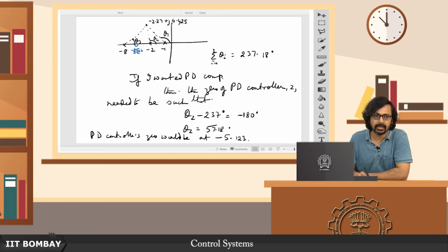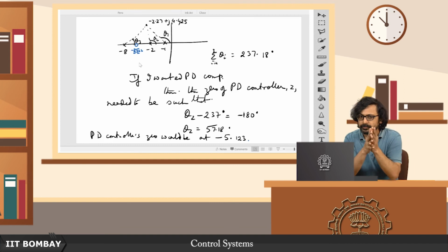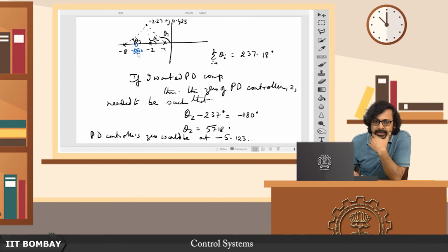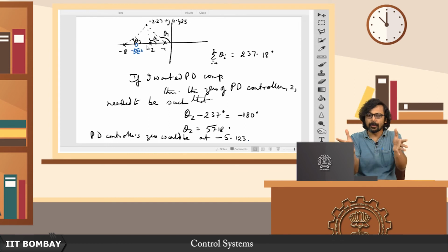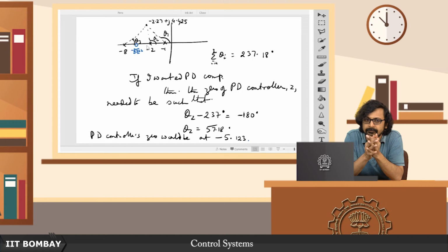The only difference being that now it might be tempting. You might often feel, okay, since I have this entire flexibility, let me try to cancel out this pole. That way, in the open loop at least, it will be a pure second order system. Wouldn't that be nice?